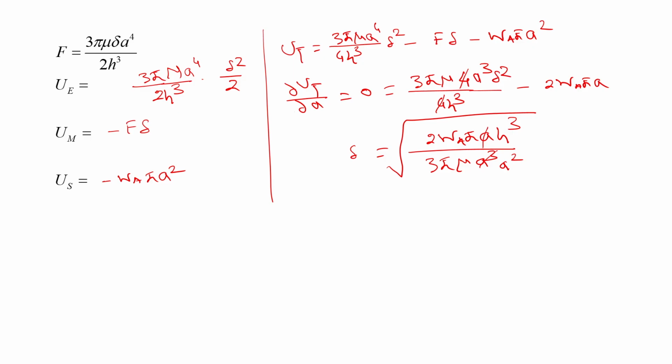So, this is the expression for the critical distance by which this top plate has to be moved upward in order to separate this top plate from the surface when there is a work of adhesion W_a at the interface. Therefore, let me write this quantity in a cleaner manner. So, this is 2, this is W_a and pi. So, pi gets cancelled. Then I have 3 mu, it is a square here, and this is h cube here.